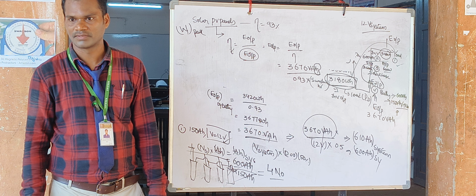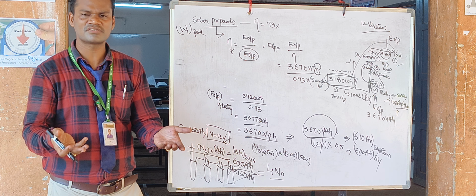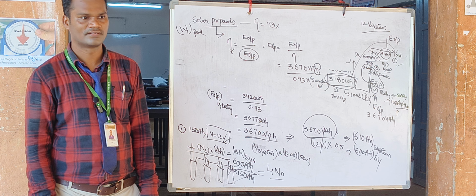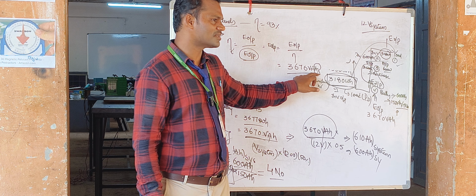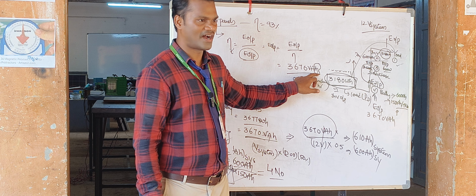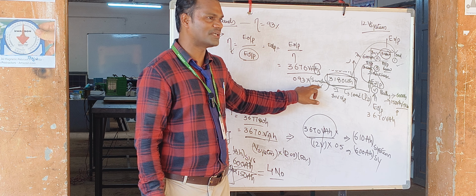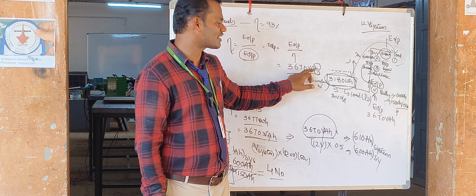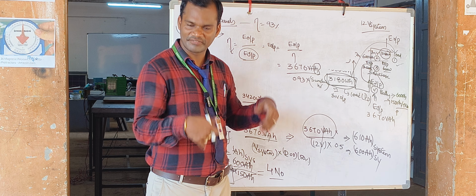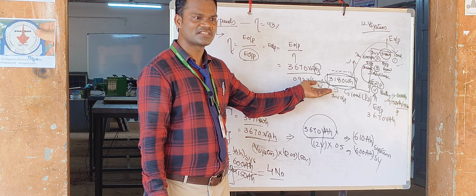available in your location. So do we need to multiply with hours, or divide with hours? I want the rating in watts, but what is the concept creating a disturbance for me? Hours. Do I have to multiply or divide? To convert this watt hour to watts, I have to divide. That's why I'm writing divide by sunshine hours.